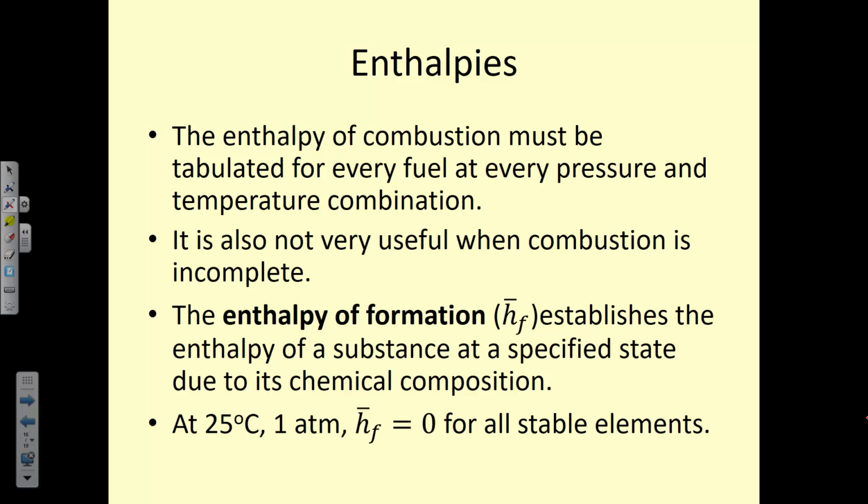So the enthalpy of combustion has to be calculated or tabulated for every fuel at every pressure and every temperature, which is pretty cumbersome, and it's difficult to get tables that extensive. It's also not very useful to us if our combustion is incomplete, because our products are not always predictable, and we don't always know the exact quantities. So sometimes trying to look at the enthalpy of combustion is a frustrating process.